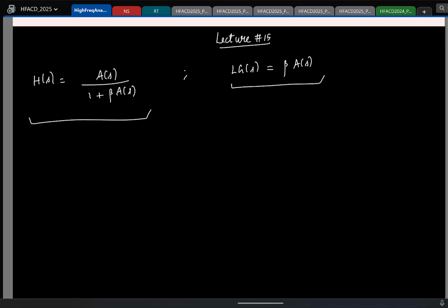And if I give you a loop gain transfer function, what might be a metric that you might use to see if it is stable or not? You have to see if the closed loop poles are in the left half of the S plane or not. But what I'm saying is you can't compute the closed loop poles all the time. So you typically try to see if you can make sense of the closed loop stability only from the loop gain. Now, if you are given a loop gain transfer function, what might be a metric you might use to quantify the closed loop stability? But that's a tool; what might be a metric or parameter that you might use?